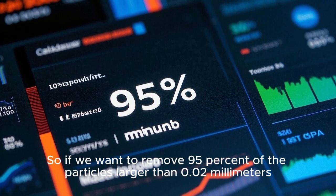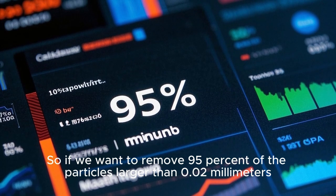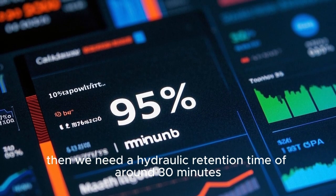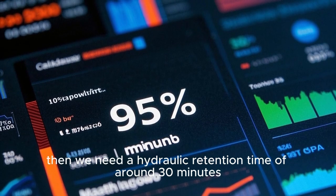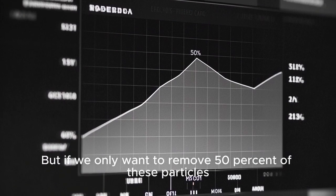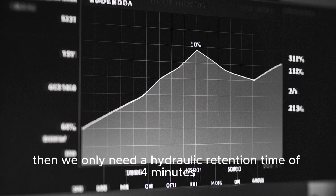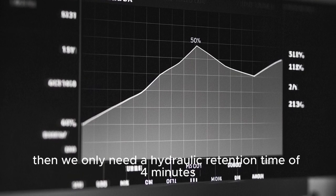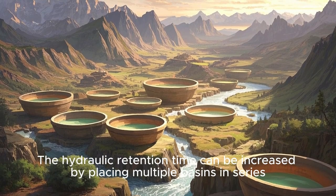So, if we want to remove 95% of the particles larger than 0.02 millimeters, then we need a hydraulic retention time of around 30 minutes. But if we only want to remove 50% of these particles, then we only need a hydraulic retention time of 4 minutes. The hydraulic retention time can be increased by placing multiple basins in series.